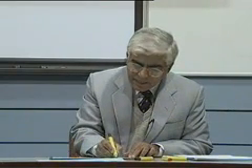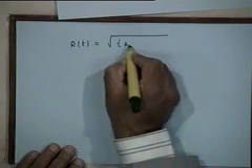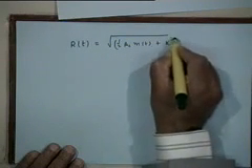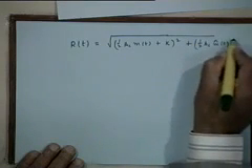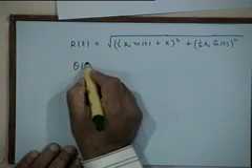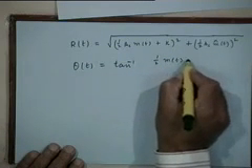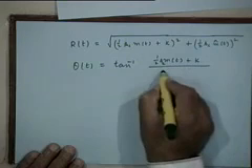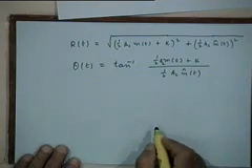So here R(t) is the square root of (half A_c m(t) plus K) whole squared plus (half A_c m hat(t)) whole squared, and theta(t) is tan inverse of half A_c m(t) plus K upon half A_c m hat(t). Inverse of this?